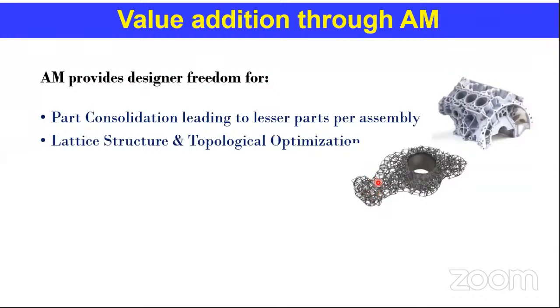The more important point to be focused on here is that, since it is challenging through the conventional manufacturing setup, people try to make this whole assembly a solid assembly, right? The moment we have a solid part, then obviously the weight of this whole component would be higher compared to this kind of skeleton structure, the so-called lattice structure.